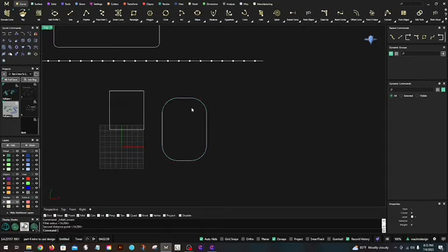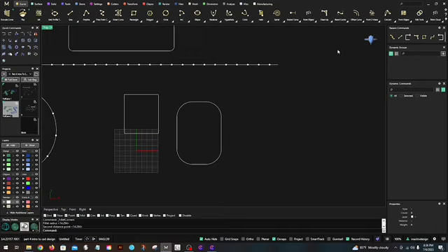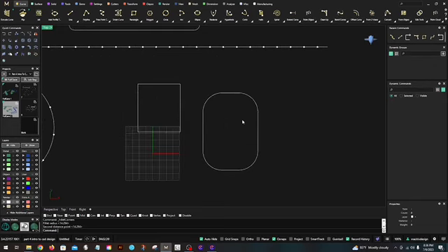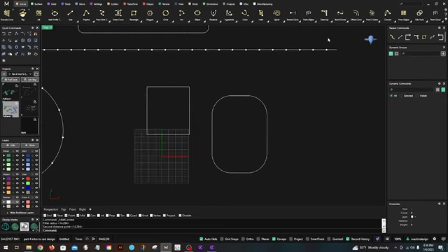Exit. If you find that you've clicked enter by clicking on your right mouse, and then you reactivate the command, you can always go into your viewport, click in your viewport and press escape, and that will get you out of your latest command. Sometimes you don't know if you have to click twice or enter twice for the command to complete it. And so that's what I do.